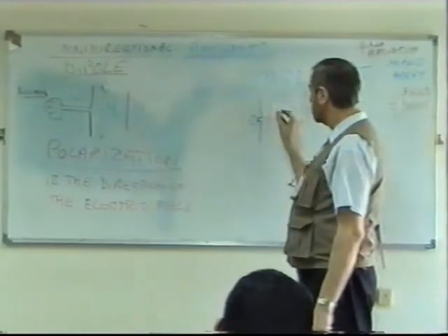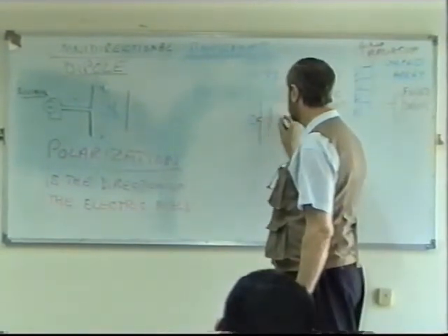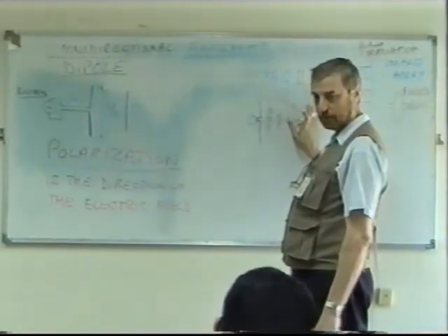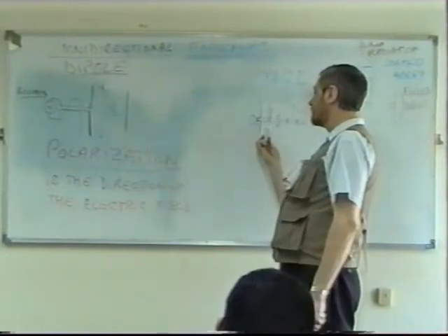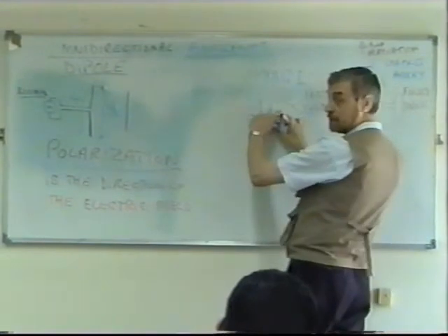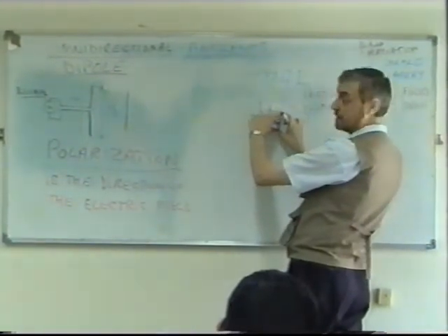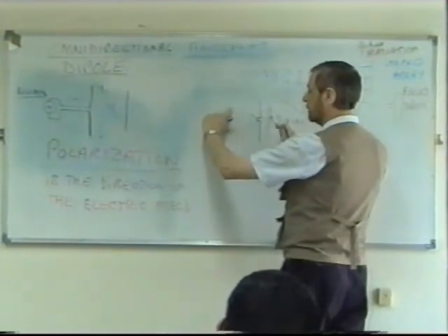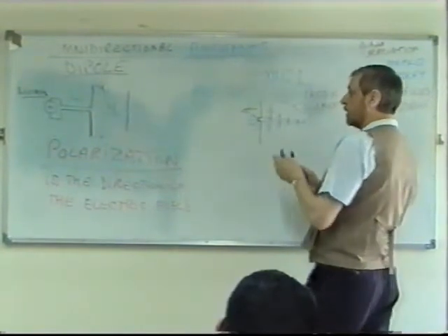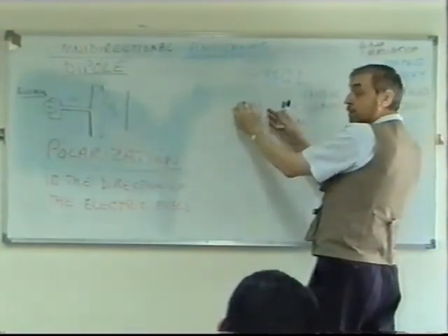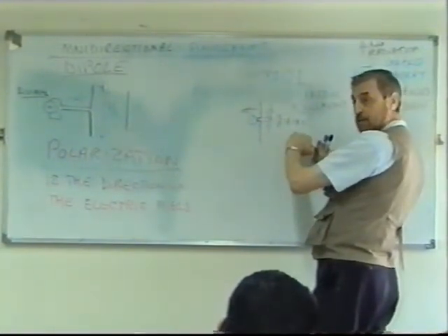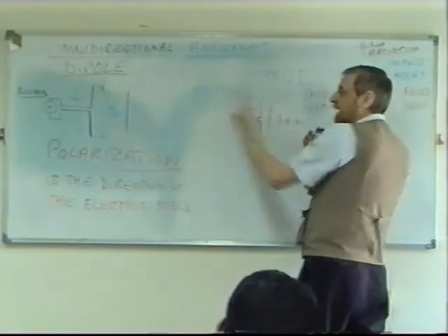But it's designed so that each of these re-radiates the signal from the original dipole. The distance between them is such that the re-radiation from these passive elements, in this direction, cancels the radiation from the main dipole. So we have radiation from the dipole in all directions, but the re-radiation from our passive element causes it to be cancelled in that direction.